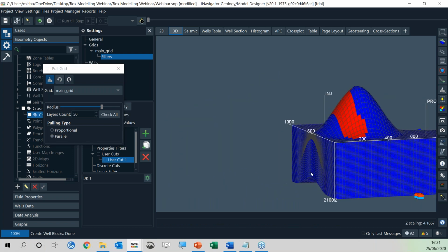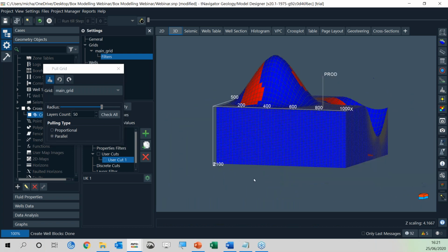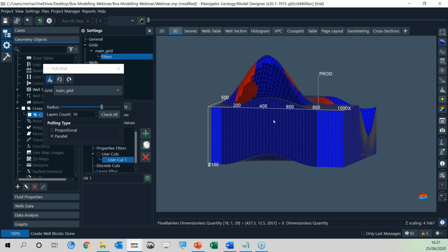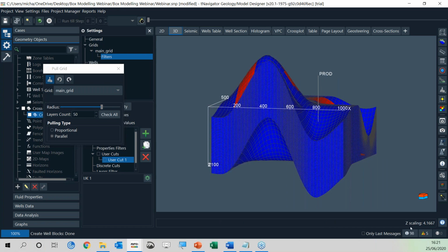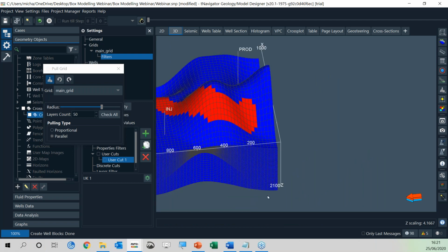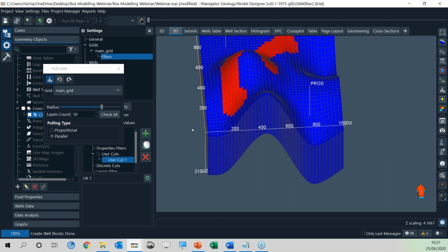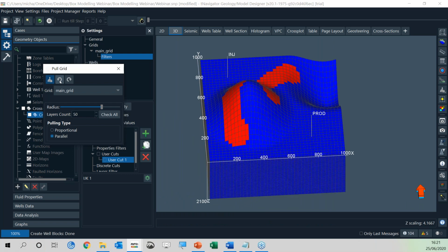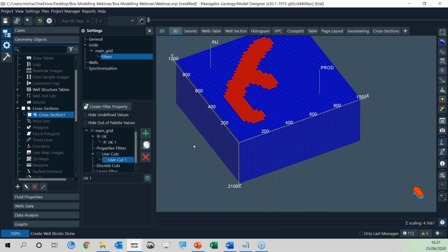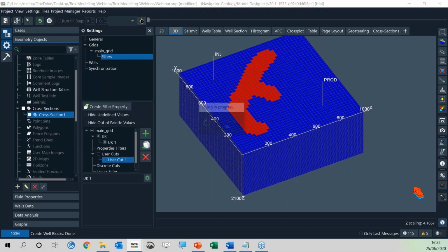This is for your more standard, let's say anticline, syncline, where you can physically just shift the model up and down like so. Okay. Again, all geologically plausible. So I'm going to undo everything I've done, go back to my box. I'm happy with my box, and I'm just going to save my model now.